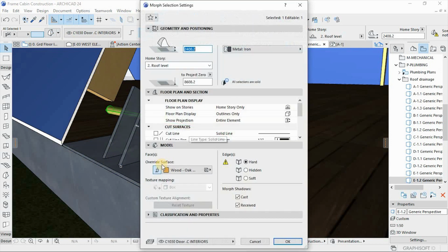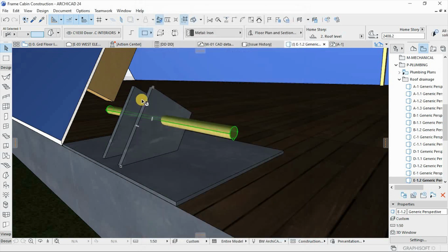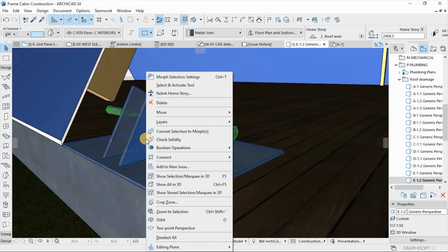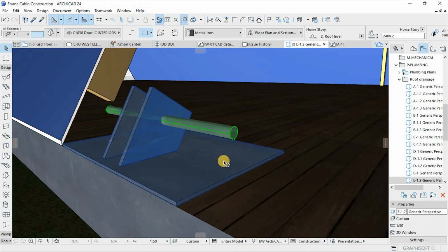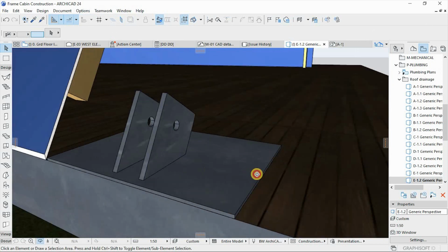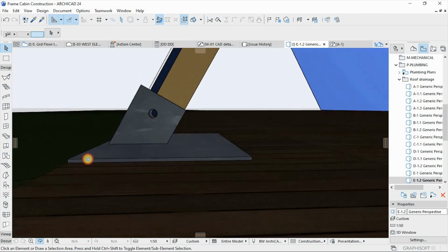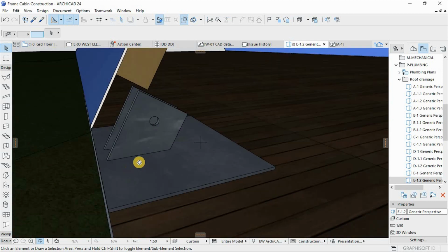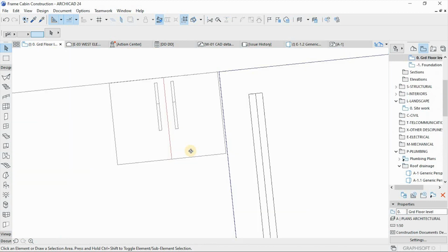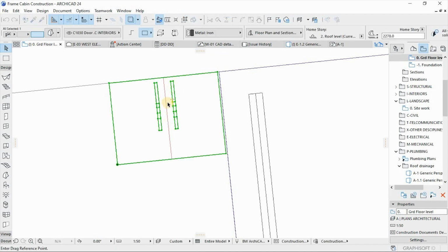And then also override the surface, then right click while the thing is selected, and then subtract, pick that one. There we go. Now we have our holes for bolting, for bolts and nuts. And then go to the top or the plan view and move this into position like so.